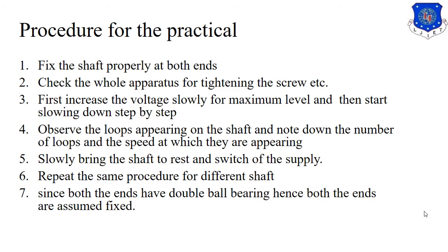Now we have to check the whole apparatus, because when the shaft is rotating, vibrations start, and each and every piece of equipment will start to get loose because of that vibration. So we have to tighten the screws, tighten the shaft, and check each and every component of our apparatus, which have to be fixed very well.